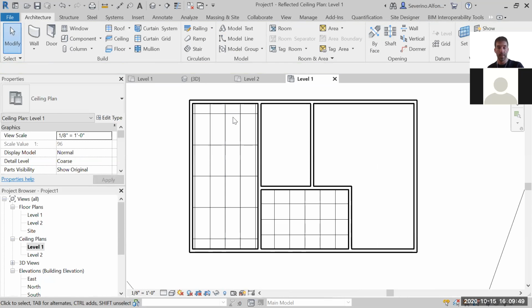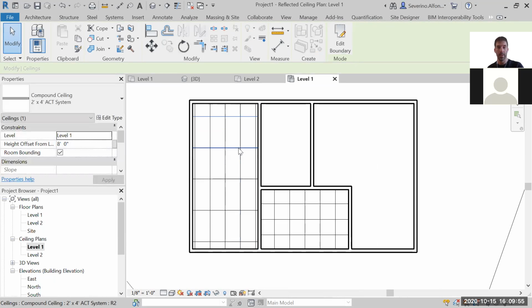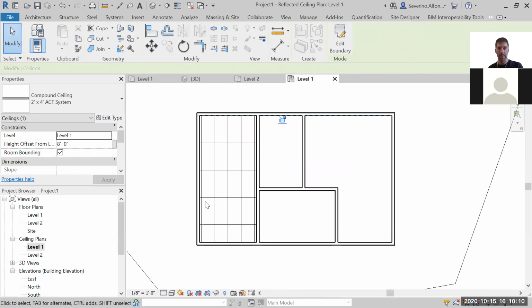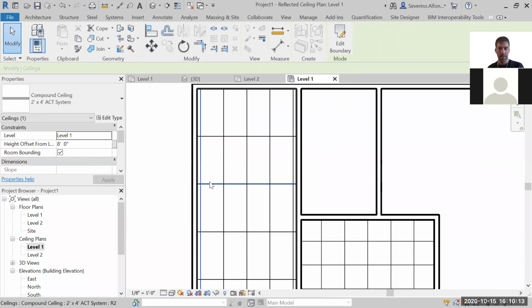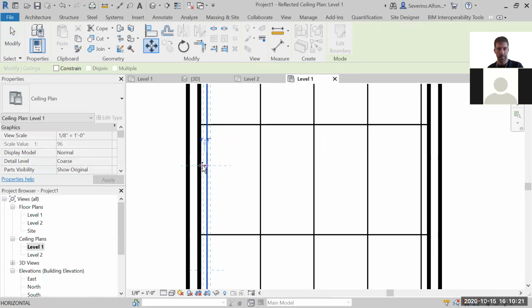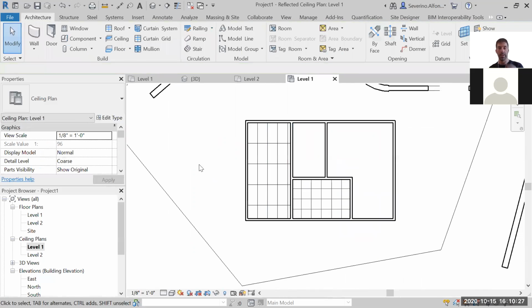Okay. You can move the grids, and this again is the compound ceiling, the one that's made of singular modules that you can lift and operate the machinery that might be hidden behind, or the lamps, etc. You can obviously move the grids to align them to the edges, so they start at a particular point and you don't have a small component of a ceiling. So you will do a move beginning at the edge, and then you will have to decide how you resolve those issues. Another story. Okay, so that gives me ceilings of different types.